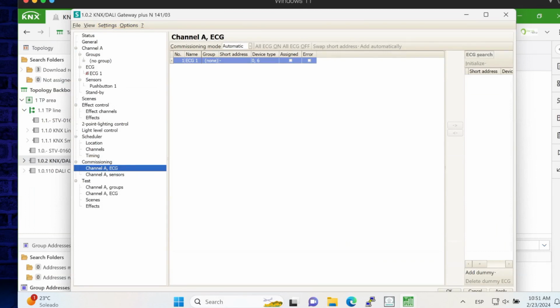Michael is saying the best DALI setup tool is ABB with their AI tool, by the way, from just a few years ago. It's not been in the market for a long time. You can set up everything in ETS and don't need ETS later for commissioning the DALI. That is correct. Michael, you say you don't want to go back to ETS, but maybe other people would say, no, I want everything in ETS because I know everything is in there. Two points of view.